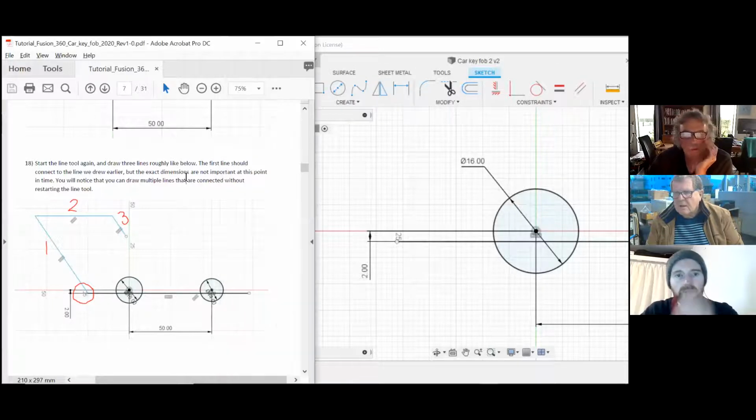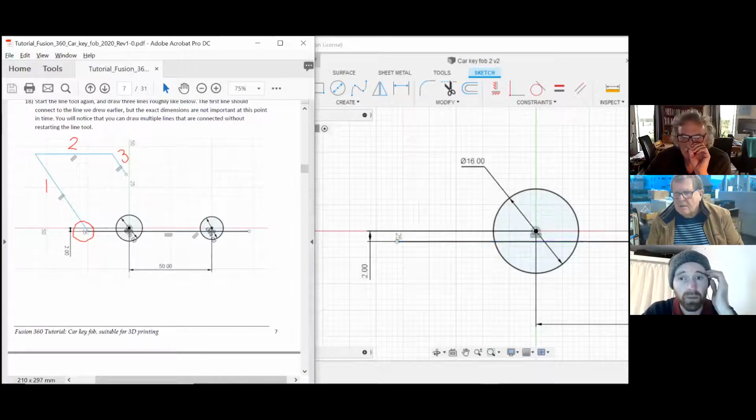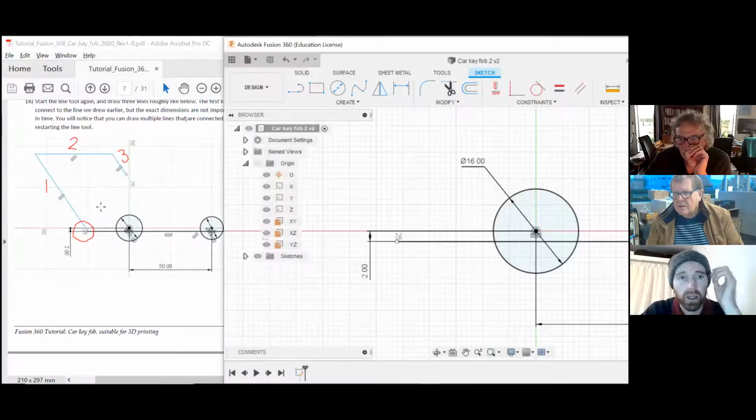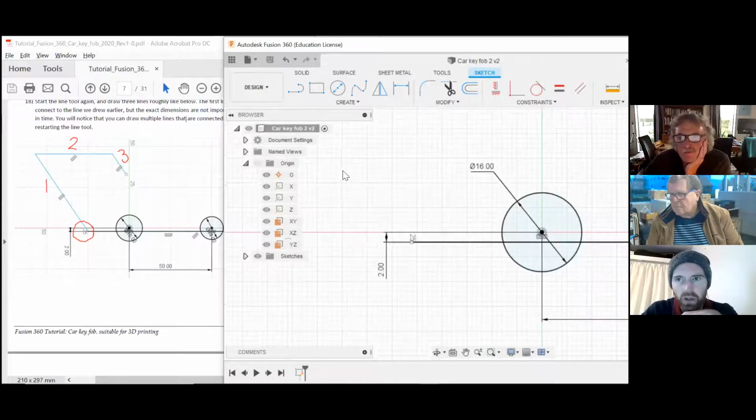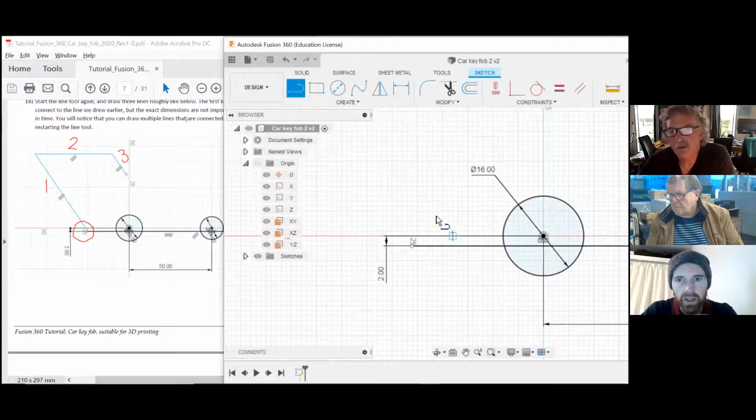Yeah. All right, so now we're going to make 3 lines for a bit of a tail rear spoiler of our car. So you notice the little symbols in the tutorial show parallel constraints. This is slightly different to horizontal and vertical. And what it's doing is it's matching the slope of the line to an already existing line. So that's like offset in AutoCAD. Yeah, I guess so. Let's see how that plays out.